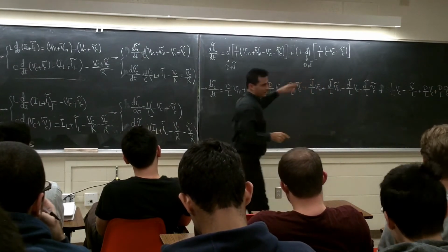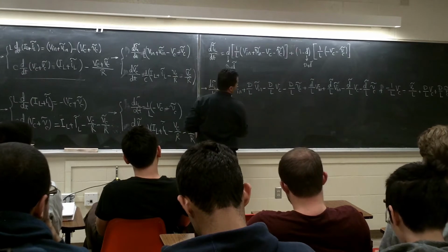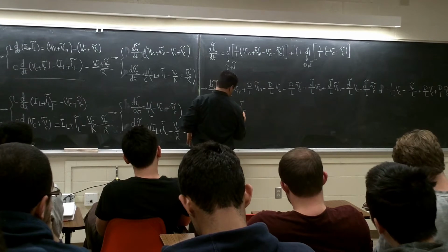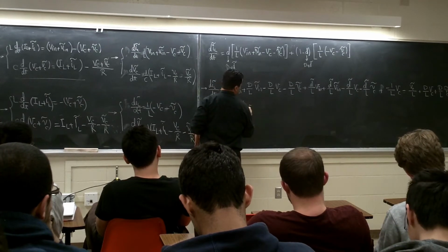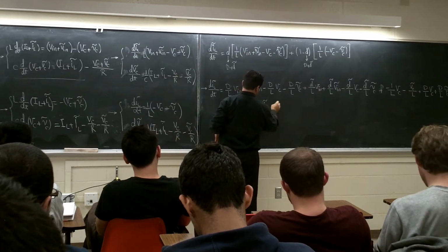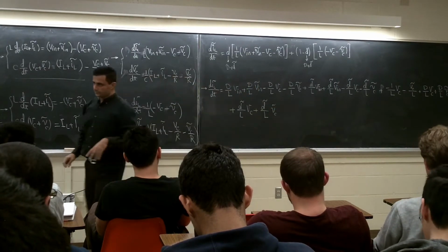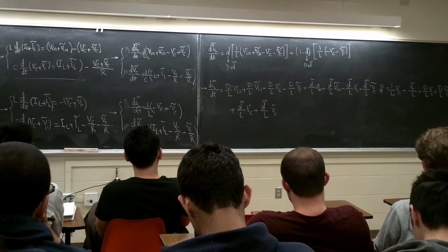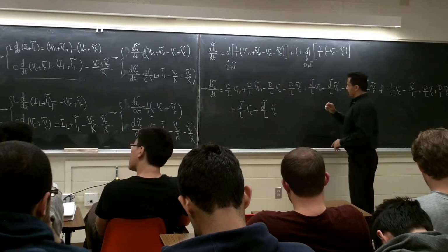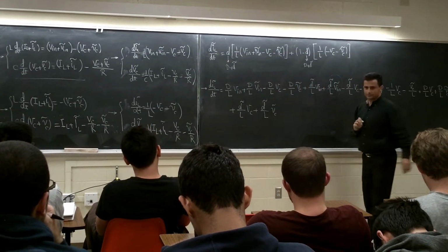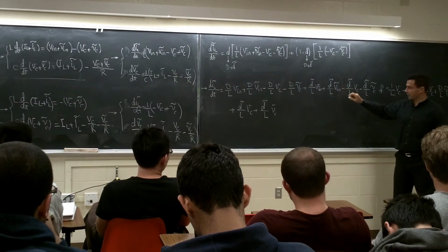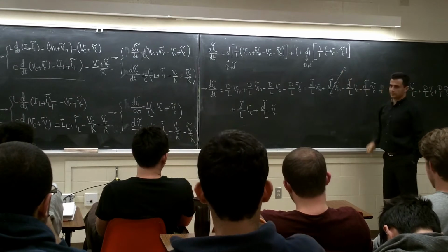Now let's go for the d tilde, plus d tilde over L Vc plus d tilde over L Vc tilde. Am I correct? Now let's see what is going to cancel out. Let's look at here. It's going to give me 0. Why? Because you have a d tilde times Vin tilde, right? So this one is gone. 0, right?